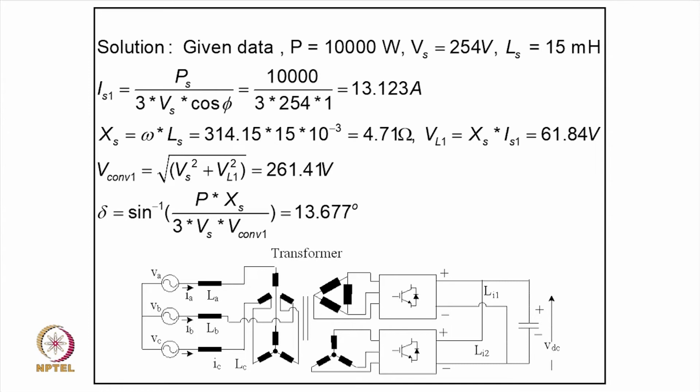Now, in this case, because it is a 12 pulse converter, we can operate at 180 degree mode of these two converters. So, the utilization of devices is more and the switching losses are less, which is normally used for very high power applications.